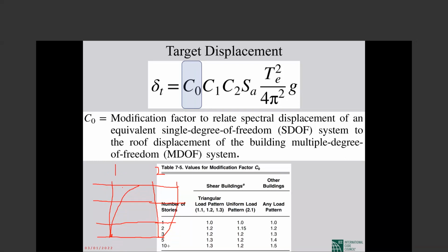And when we look at the elements, there is no really bending behavior in elements. But this one bay frame mainly goes through axial deformation in those two columns that it has. One is in tension, one in compression, but generally the building's form is bending. So when we name it bending or shear, we don't talk about the element type of behavior.